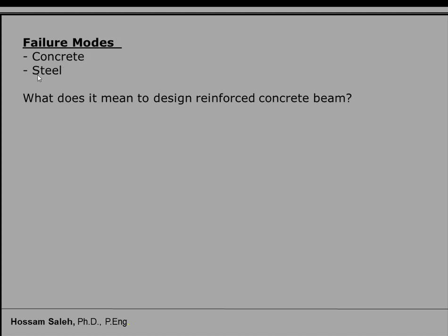The steel failure, before it happens, starts to elongate because the steel is more ductile, and before reaching the fracture of the steel bars, the steel will have elongation, and this elongation will be translated into cracks of the section. So we can see cracks in the beam, and that tells us, you know what, something here has to be checked, and then we can repair the beam.